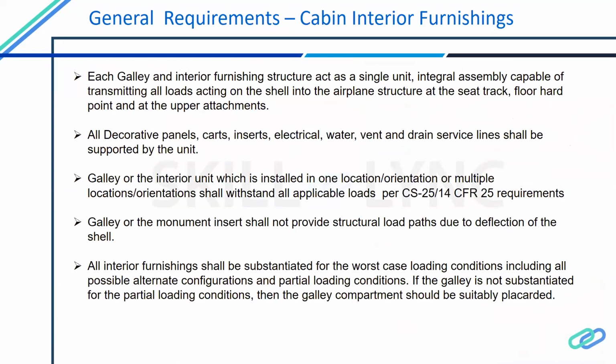Practically that will cause a clash with a seat, or a clash with any other compartment divider wall, or cause an egress problem, disturbing the passenger evacuation way and things like that. They should not undergo such deflection. So that's one of the main things that they are putting forward to us.